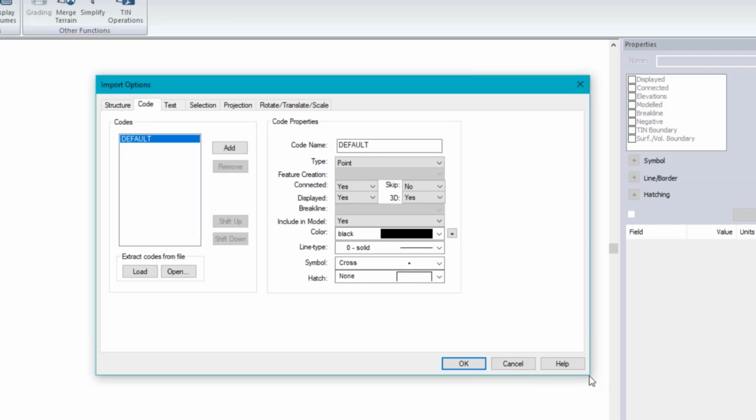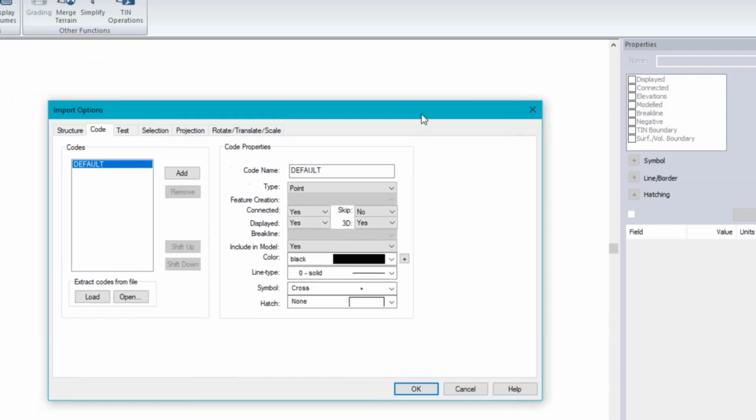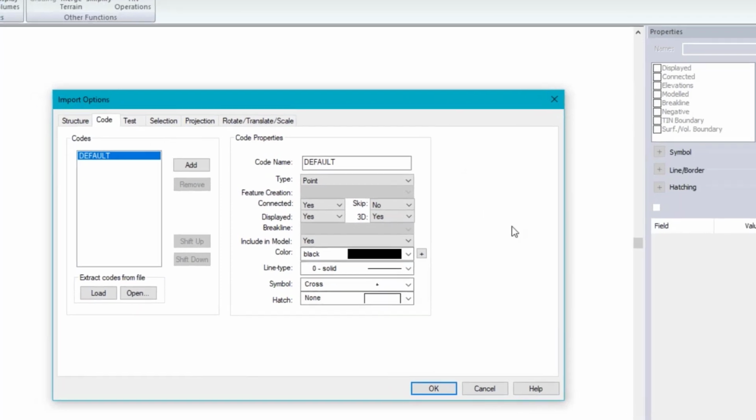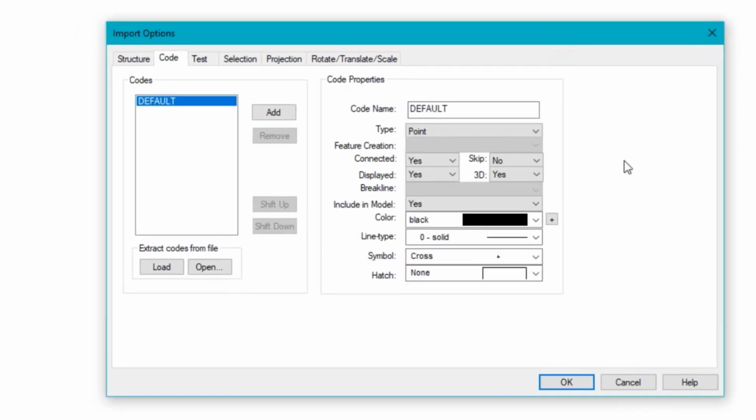Here's where the real work begins, in the Codes tab. So in the field, my surveyor picked up points with his instrument, and every time a point was entered, he tagged it with a piece of text. I think on modern instruments, this is as easy as picking from a drop-down list. Here's all the point codes that are in the file. Click on the load button. There they are.